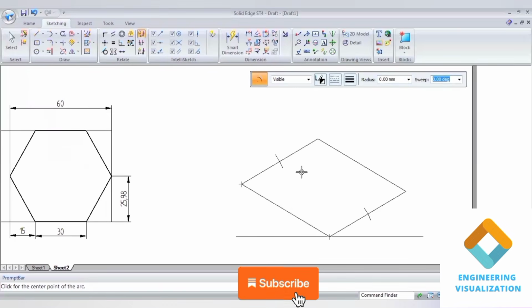Okay. After that, at the edges we have to cut an arc length of 15 mm from the corner ends. Okay, 15 mm. From this side also 15. Cut it. Same way from here also. Cut it for 15 mm. Same way you can do it here. Radius of 15.